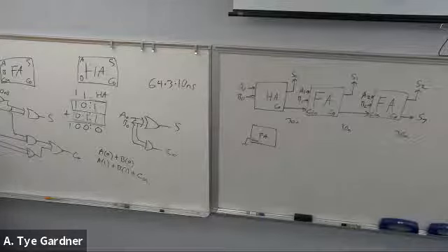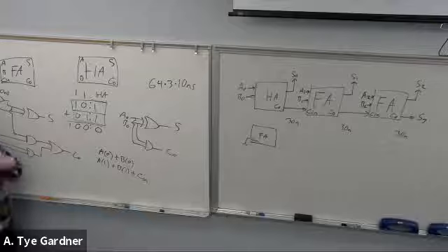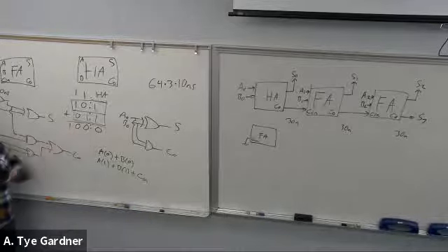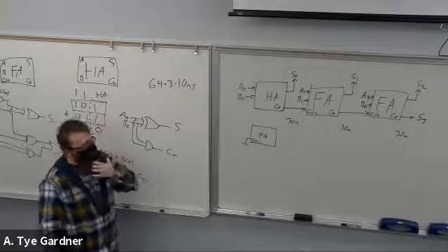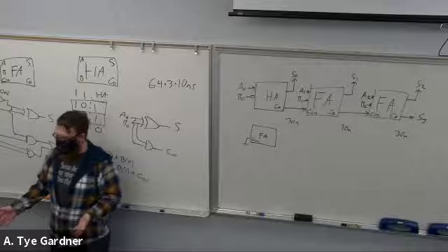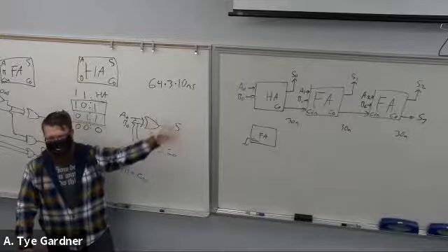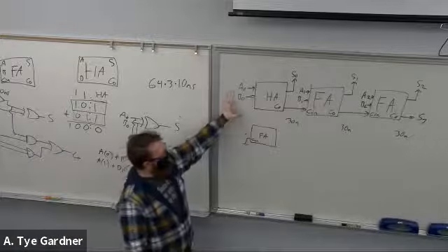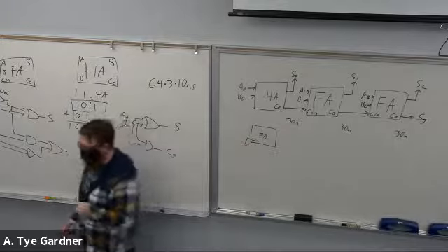And later we'll deal with, and I'm not sure if it will be in this class or if you'll have to wait till 3610, it just depends how much material it is, how we speed this up, because this is not really acceptable for modern high-speed circuits. There are solutions to this, and as you may suspect, we're in engineering, so it's trade-offs. We can make this go faster at the expense of cost or size or complexity. We'll get there. But for now, understand this is called a ripple carry adder. Its main deficit is it is not fast and it doesn't scale very well.